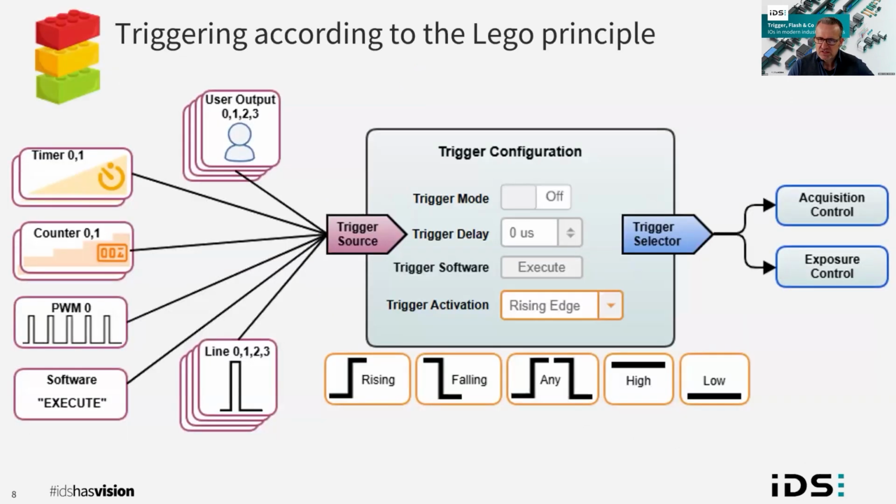However, since GenICam and SFNC, triggering an image capture is no longer limited to one external source. By separating the hardware device inputs from the triggered software functions in the camera, electrical input signals become an abstract signal definition with a wide range of use. Counters, timers, generated pulse width modulated signals, or even software are possible signal generators.